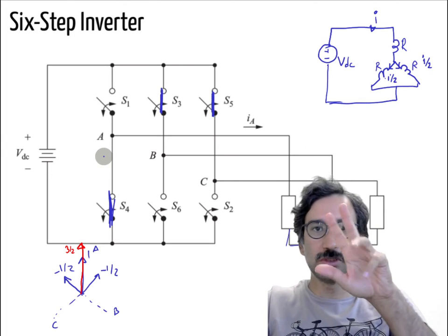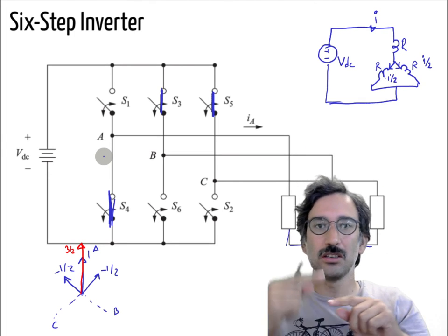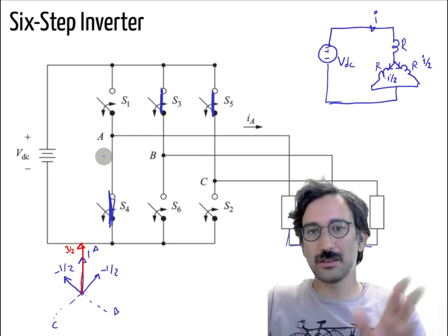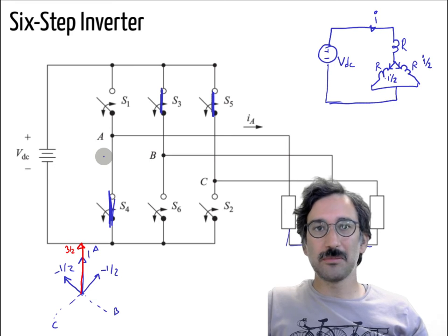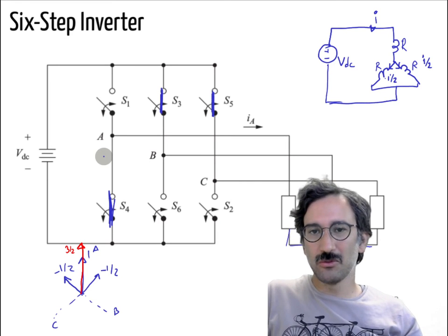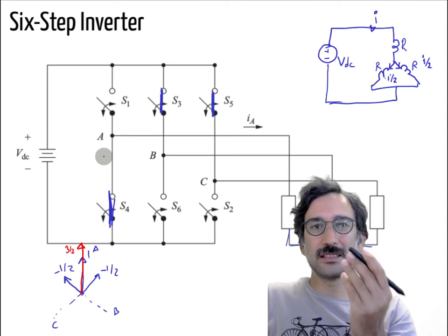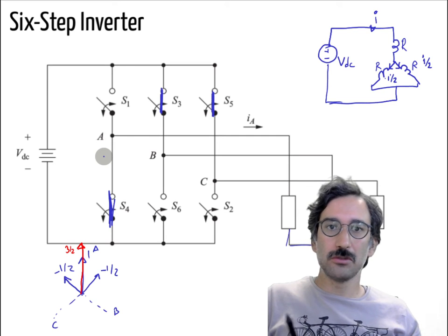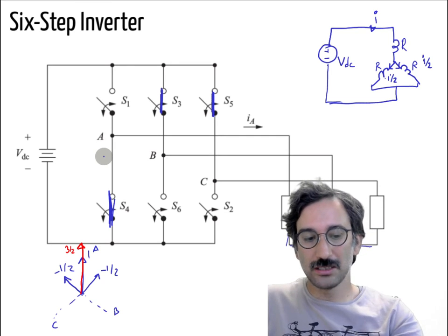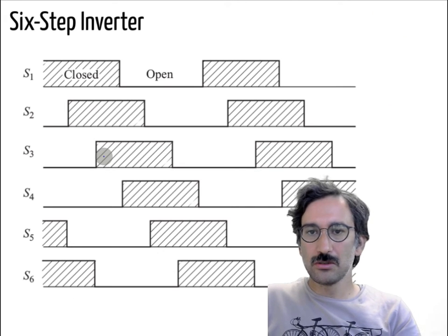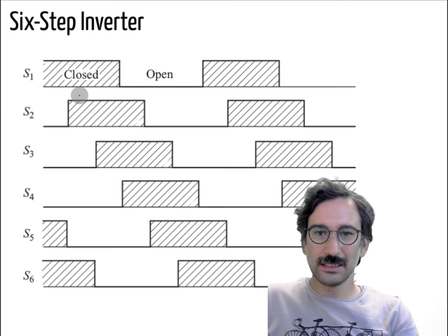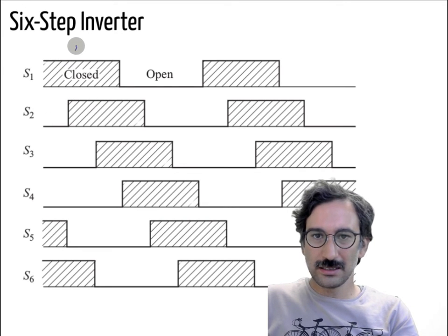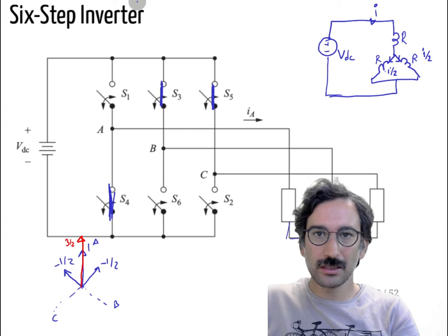If you just do that according to the rotor's position, you can rotate the rotor at specific positions, and that is the 6-step inverter or square wave inverter. It's called 6-step because there are 6 different switching states. If it is driving a motor, those 6 switching states correspond to 6 different rotor positions or MMF positions. So again, if you just look at the sequence, at first let's start at that instant. Here, if I just go back, clean that part.